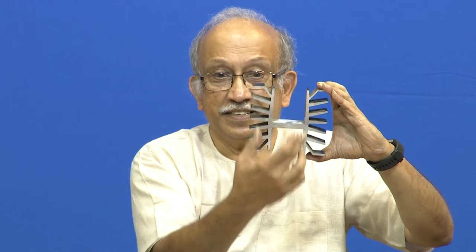If you are one of the aero modelers, you must have heard of the word spinner. In front of a propeller, usually you have a spinner. That spinner deflects the air, and here we do not need such things because of the amount of space. When you put these things together, you will see that these fins are directly in the air flow, and this area and this area have been reserved for components.